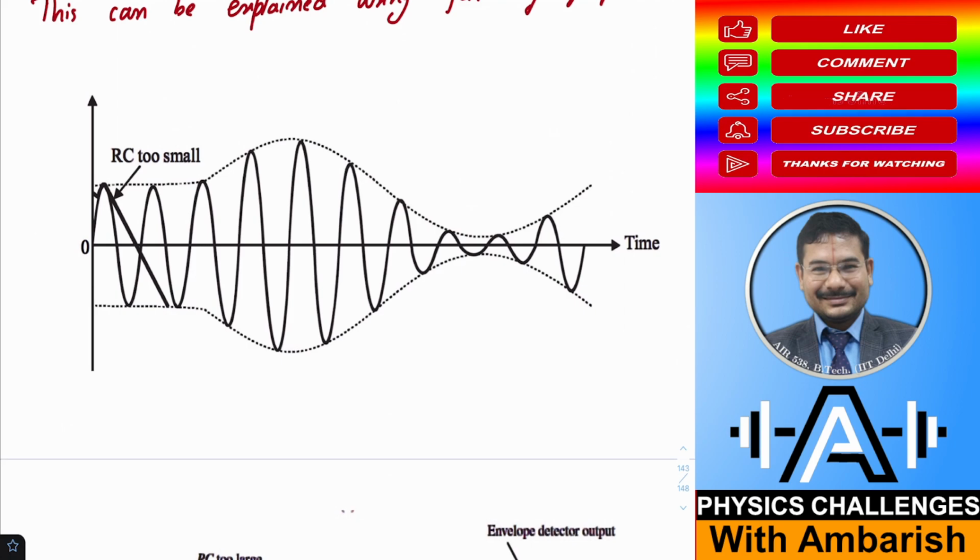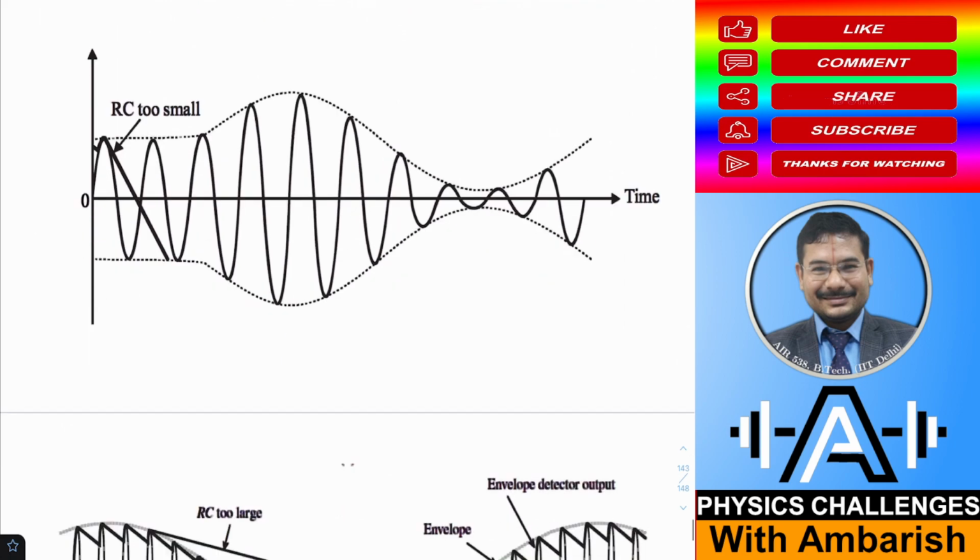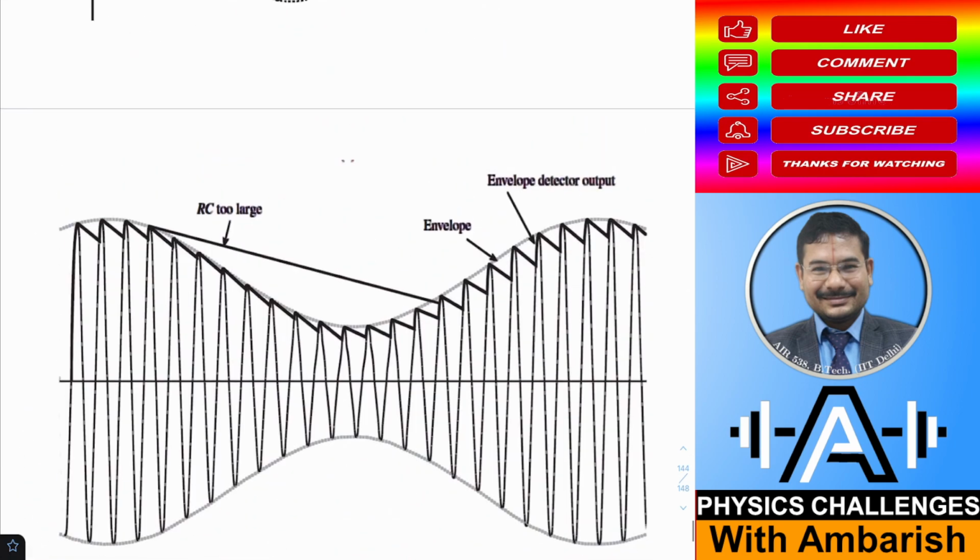Whereas if RC is very large, that will create another problem. So again, suppose RC is very large. For example, here it hit the peak, and then capacitor started discharging. But when the capacitor was discharging, it turns out the message signal peaks were all lower than the capacitor voltage itself, right?